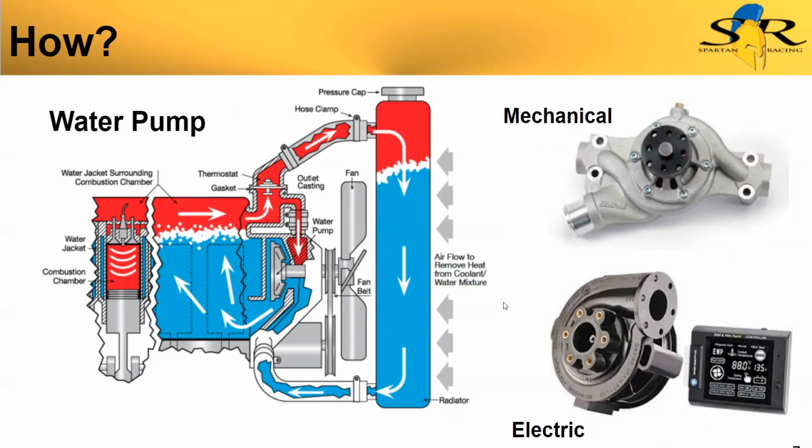The pros and cons to those: mechanical, you're not wasting the conversion from mechanical energy to electric energy and then back to electric energy to mechanical energy to power the pump. The benefit to an electric pump is you can more precisely control it, and you can eliminate some of the unnecessary drag at high RPMs that are going to be there with a mechanical pump. And if you spin a pump too fast, it's going to cavitate, stop pumping altogether, and start eating itself. And that's bad.